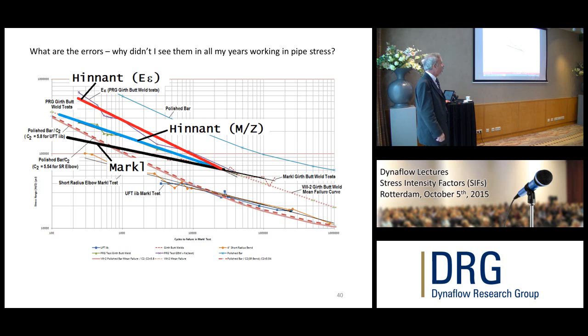The fatigue curves that we're using have a strain concentration factor already a part of them because they're cantilever tests. What that says to you is, if any of you are college professors and you want to do really accurate fatigue tests of girth butt welds, and you decide you want to use the college professor approach, which is 4-point bending, a really good, very dependable bending test, you can't use that for a piping code, because 4-point bending is going to give you this as a fatigue life. If you run a cantilever test, you'll get this as a fatigue life, because cantilevers have strain concentration factors in them when the strain range gets above 2 SY. So be very careful taking somebody's fatigue test data and just throwing it into a pipe stress program. There have been enough mistakes made in the last 20 years when people try to do that.